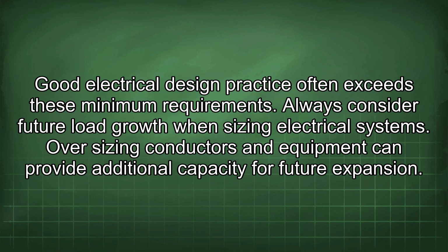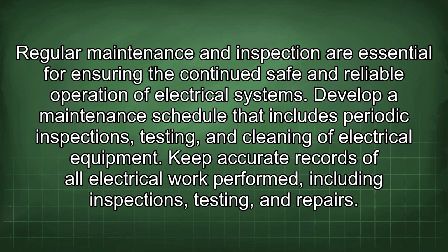Always consider future load growth when sizing electrical systems. Oversizing conductors and equipment can provide additional capacity for future expansion. Regular maintenance and inspection are essential for ensuring the continued safe and reliable operation of electrical systems. Develop a maintenance schedule that includes periodic inspections, testing, and cleaning of electrical equipment.